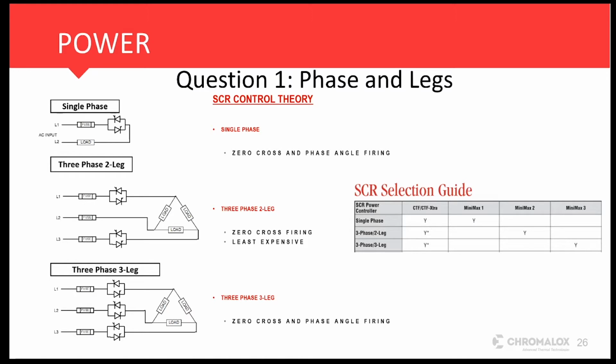And then, the first real question after you get to either a contactor or an SCR, for the purposes of this presentation, we're going to dive deeper into selecting an SCR. Question 1 from there is, how many phases and legs? This basically will just match up with whatever the actual heater is as far as the phases.